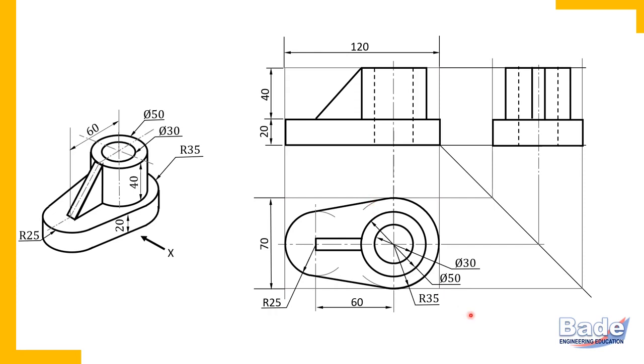and finally symbol for first angle method of projection. You need not write here front view, top view, side view. Once you have drawn this symbol, it is clear that it is front view, top view and side. Also, first angle method of projection, top view appears below front view. So even if that symbol is not there, one should understand that this is top view and first angle method of projection is used. But still it's better to show, because it is practice. It is better to draw this symbol.